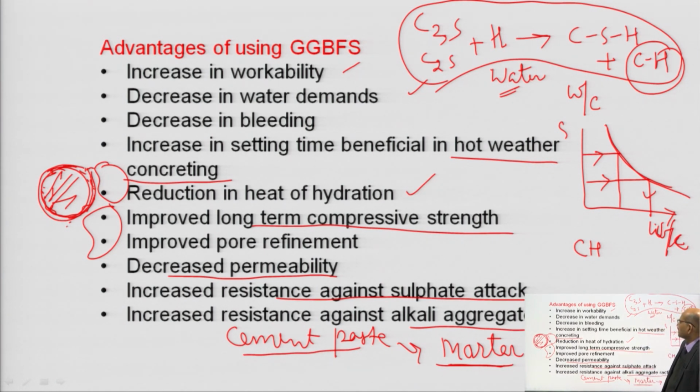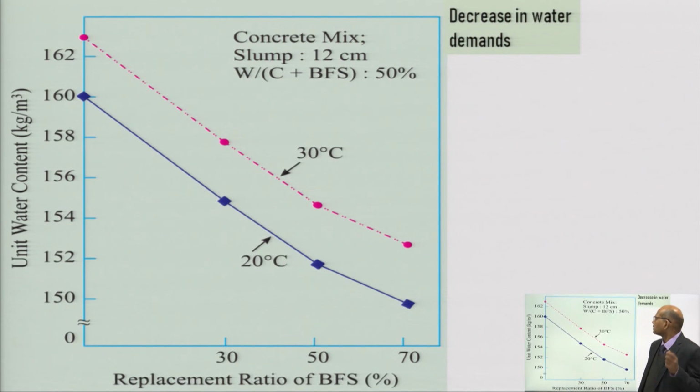What is the disadvantage? If you have to do cold weather concreting, the rate of reaction is slow and the heat of hydration is slow. So, in that case this may not be very suitable where we have to go for cold weather concreting. So, these are the advantages and disadvantages, and I will be discussing a little more here.